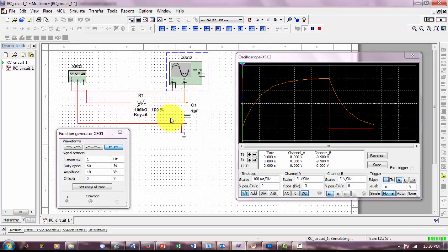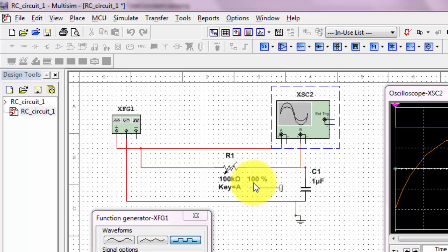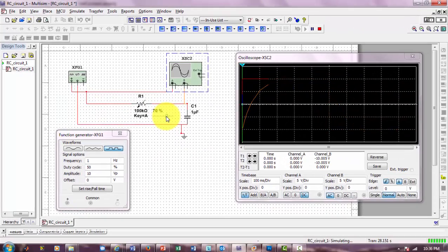And we can see that it's charging and discharging. Notice this is at a resistance of 100 kilo ohms. Now suppose I decrease the resistance. We should get there faster. So as I decrease the resistance, what are we doing? We're reducing the resistance and reducing the time constant. So we're going to get there faster, and you can see the effect on the oscilloscope shown here, that it is charging faster. Okay? And that's the result when it's at 5% of 100K, which is 5K.